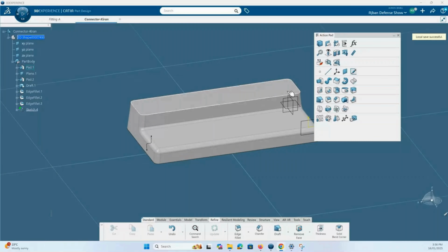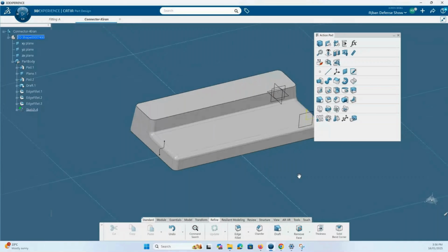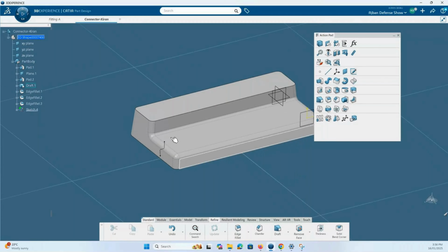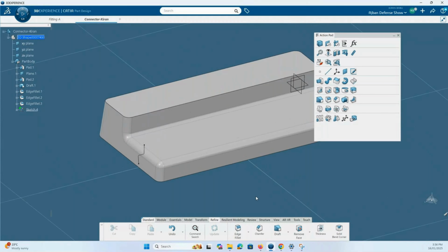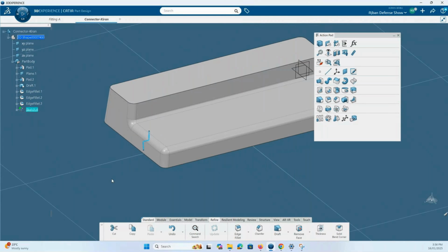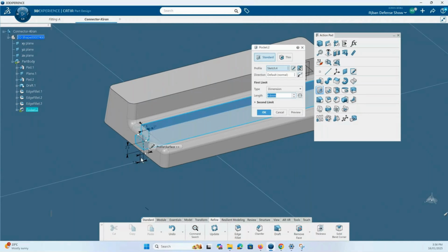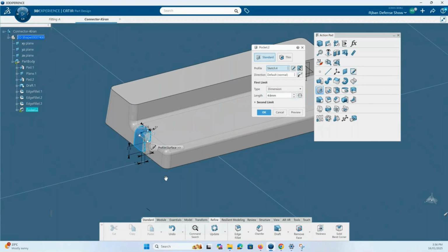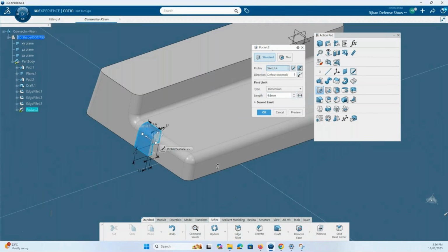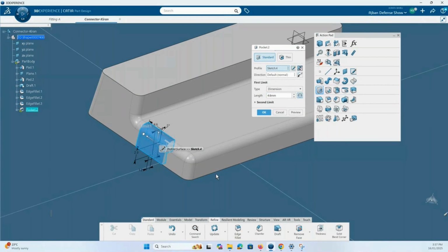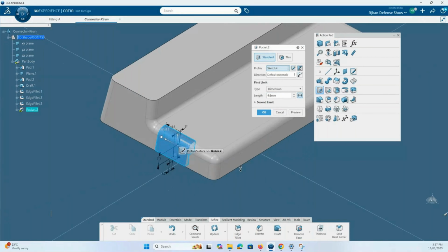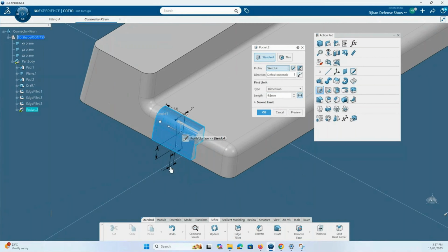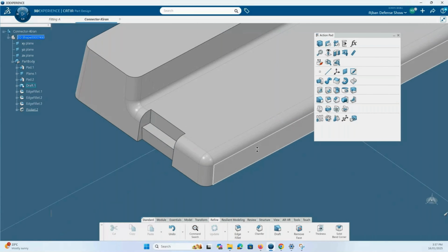So, starting off where we left, we were trying to create this recess here. I'm going to go back to that sketch and click on pocket and change it up to see the pocket to be here. I want to extend it here to see if I have the correct dimension. So 2.6, 2.6, 1.2, 3, and 5 degrees. Perfect. So I have the recess here.